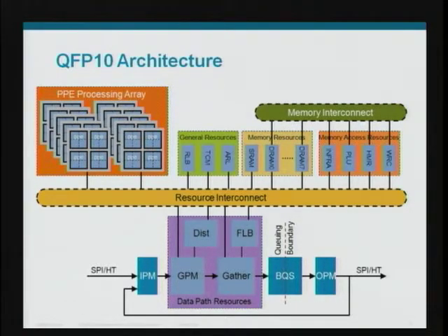From a packet flow standpoint, packets will enter and will be distributed on a who's-available kind of basis. And a key architecture point was we very much wanted to have the programming model be as simple as possible. So we use a run to completion programming model. We don't do flow-based load balancing. When it comes to all the various coherency and flow ordering, we've built hardware blocks that assist with managing those data structures and tried to make that as simple as possible from a software standpoint, so that they're all accessing a global table. We've looked very carefully at our applications and tried to minimize the load on the software programmer.